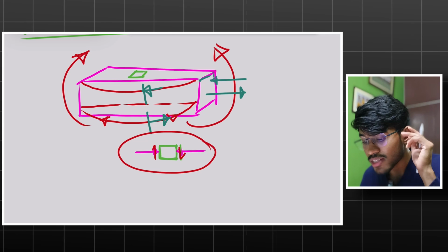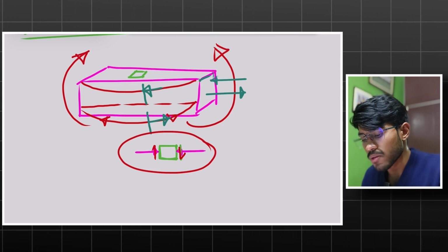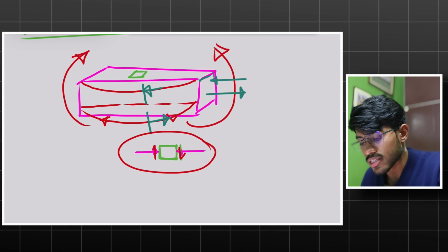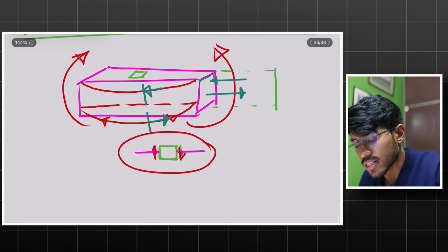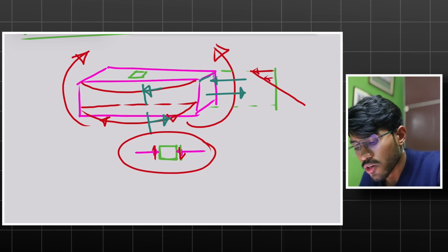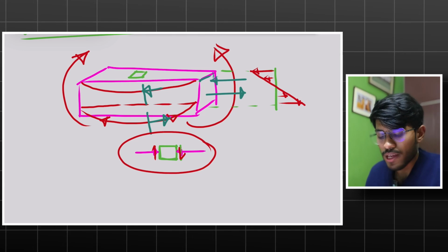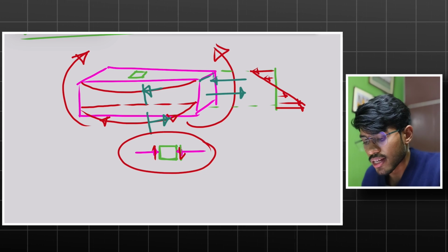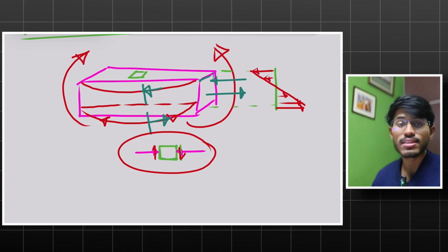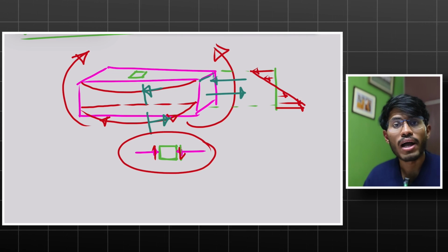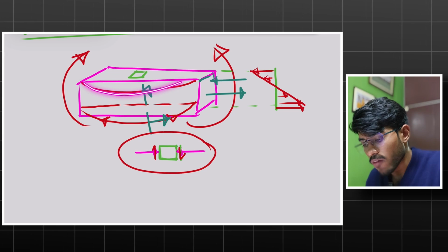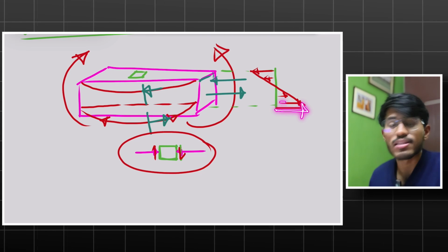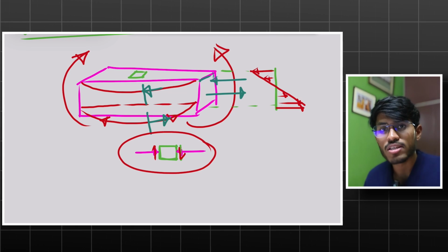I am asking you this because in BARC they asked me, can you draw the stress distribution for this beam? If I extrapolate this, the stress distribution will be something like this, right? And we all know this. Then they said, tell us, is this tensile or is this tensile? I told them, sir, this will be tensile. They asked me why. I answered by intuition: if I see the type of bending here, it will bend something like this, so this part will be stretched, and that is why this will be tensile. They were very satisfied. So this type of visualization should be there.